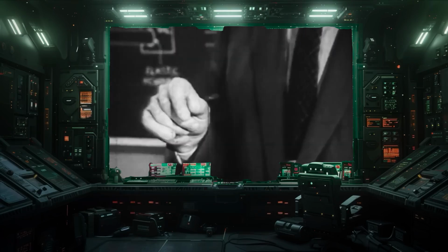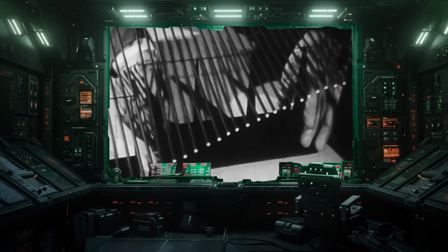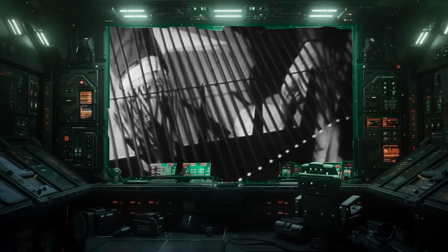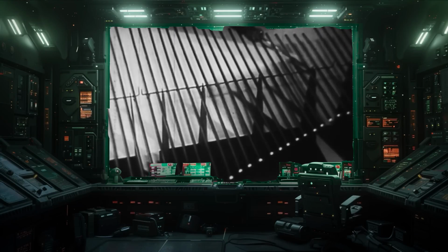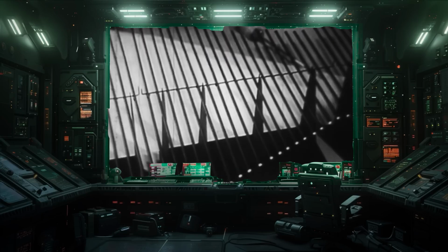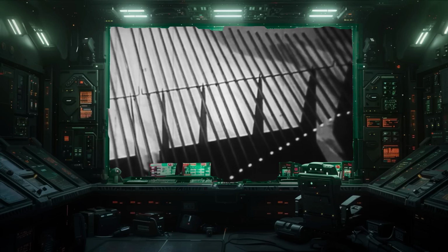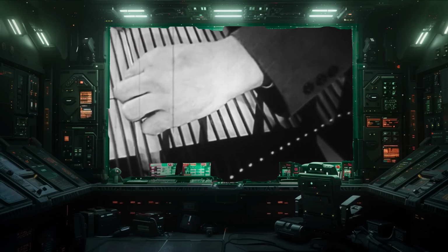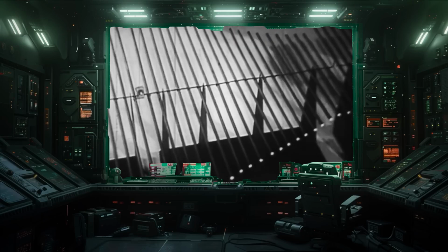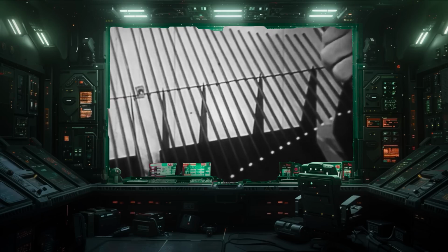The mechanical analog of a megaphone is a section of the wave medium whose cross-arm length at the two ends matches the cross-arm length of the two machines that I am trying to couple together, with a gradual taper in between. A tapered section transformer such as this will match impedances over a relatively wide band of frequencies. It is effective also for use with single waves and pulses.